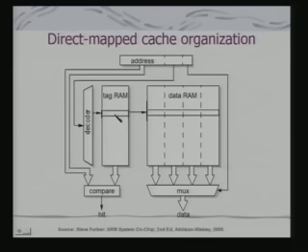So, this tag RAM is used to get the tag, and this is compared with this part of the address. So, this tells you a hit, and accordingly the data would be provided. So, this hit will be used for enabling the appropriate input line of the multiplexer.